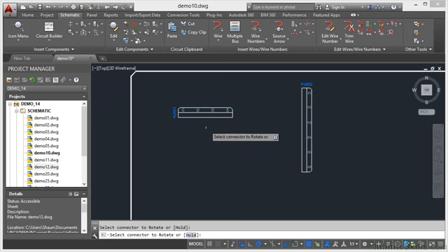So I'll just rotate that through each time again, 1, 2, and 3, and we're back to where we were before. So remember that yes and no when you're rotating your connectors. It can be really useful for the attributes because sometimes you might want to maintain that orientation. Other times you might not. So that hold option allows you to either maintain the orientation or not, as the case may be.